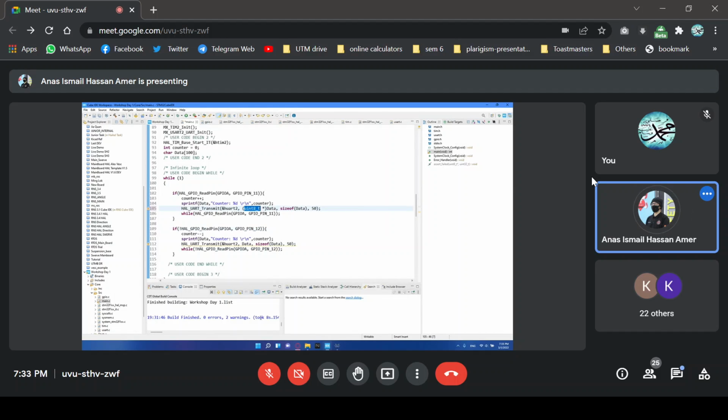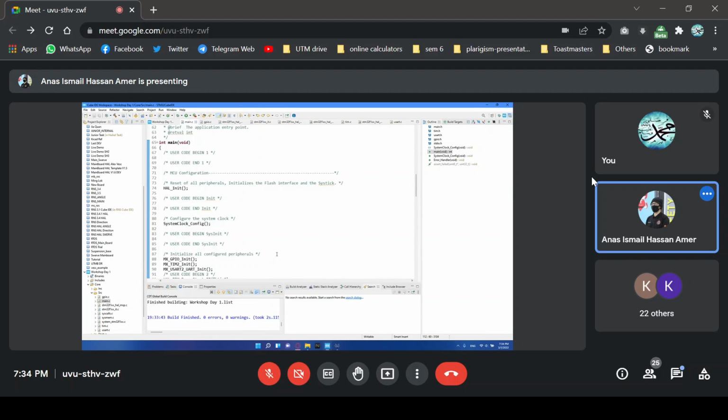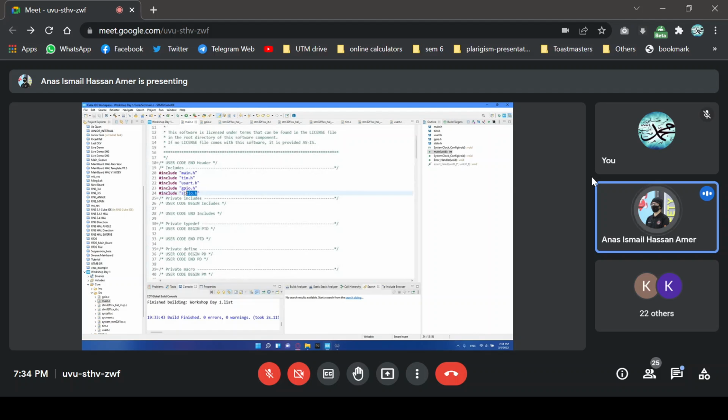So data is now an unsigned int of 8 bits and should remove the warning. They're the same size, carry the same data, so it shouldn't matter. Test this one. Then Control B again, the warnings should be removed. So any other questions regarding the code? Don't forget to include the stdio.h to use the sprintf function.